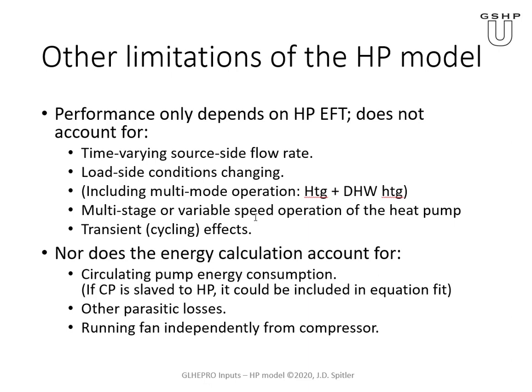Also, the energy part of the calculation, where we estimate the electrical energy, doesn't account for circulating pump energy consumption. If the circulating pump's slave to the heat pump, you could actually include that in the equation fit. You could add the power consumption of the circulating pump to the heat pump.